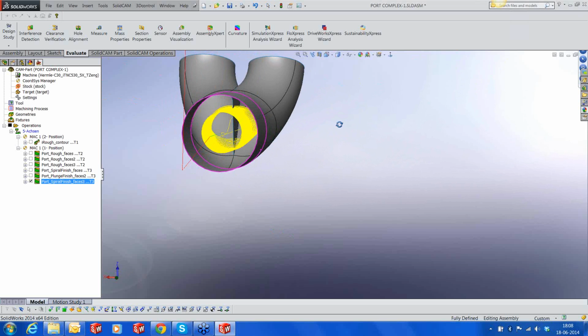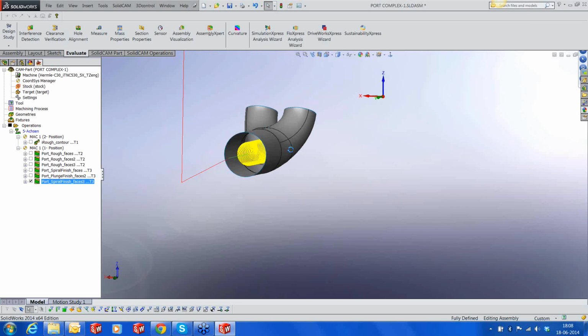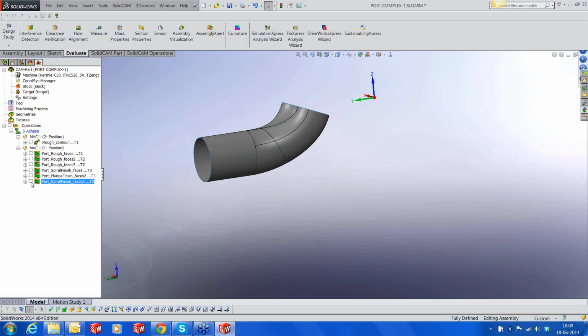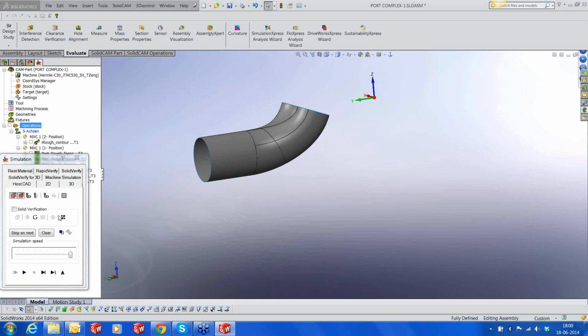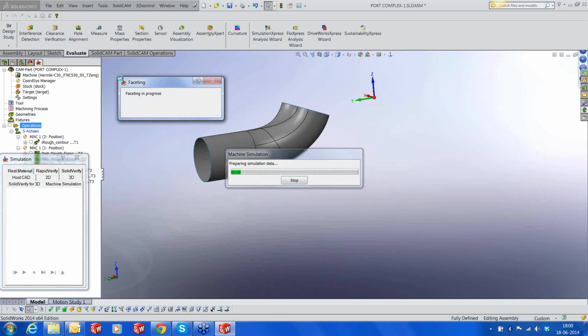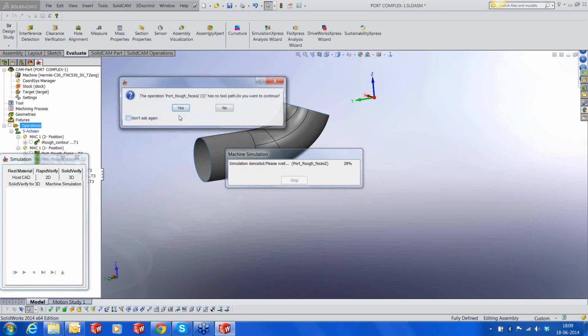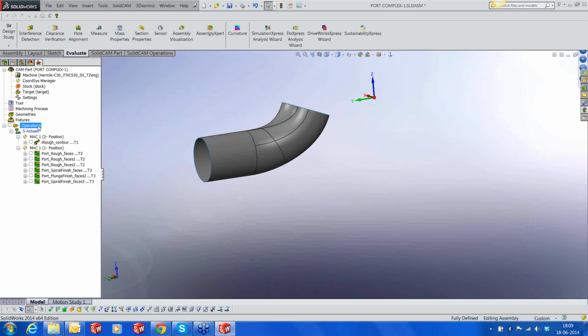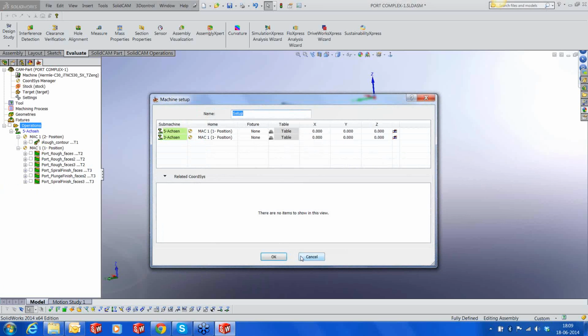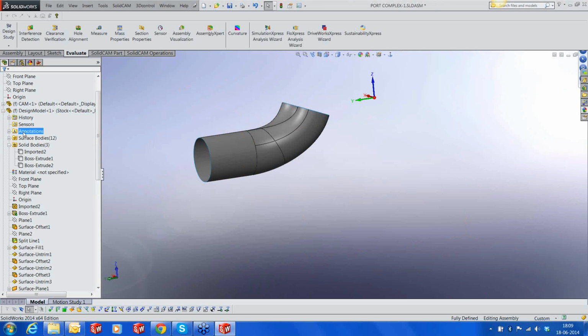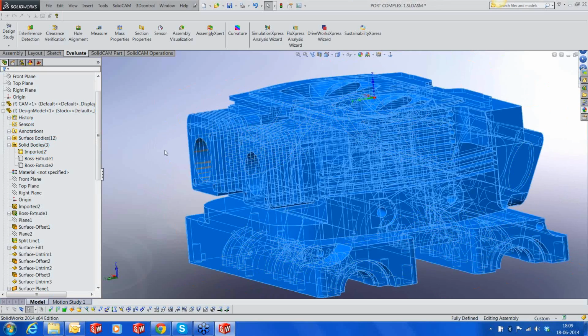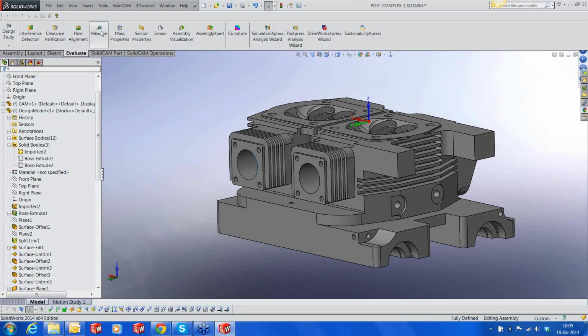We've done the machining now for the main side, and now what I'm going to do is set all of that to simulate on a machine. So we're going to move this to the machine. Obviously we have some issues which I did not take into consideration. We need to do some setup to push the part, because we have a part which has a height, so it has to be above the bed by a certain height.